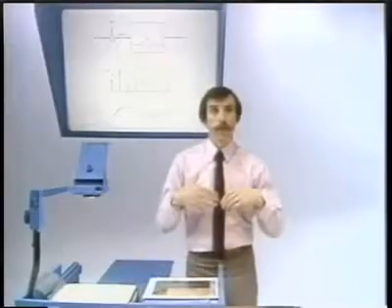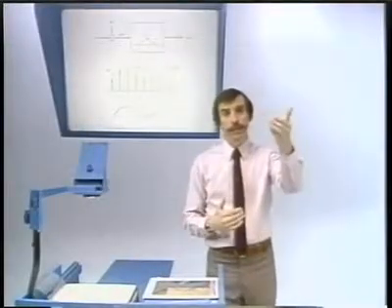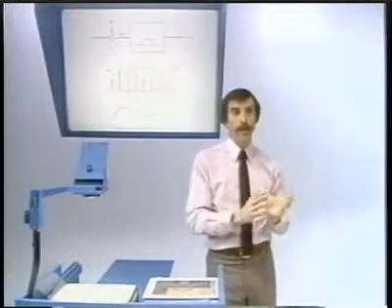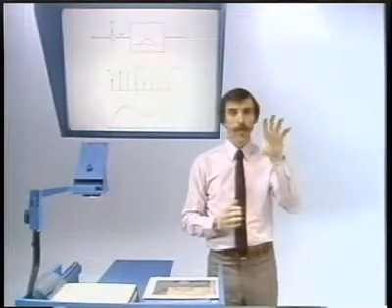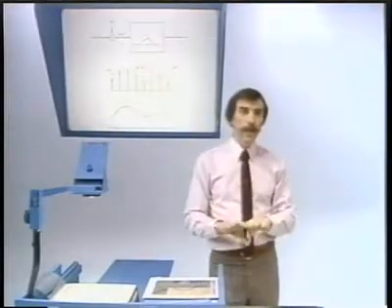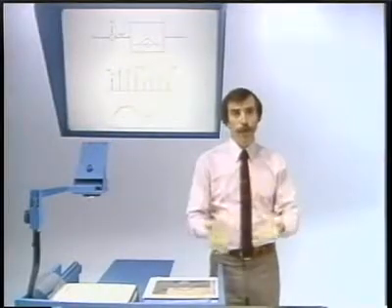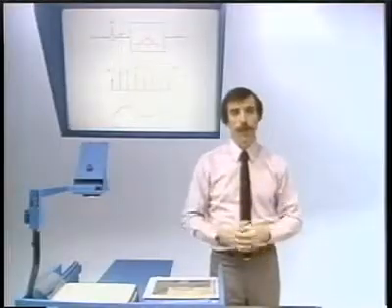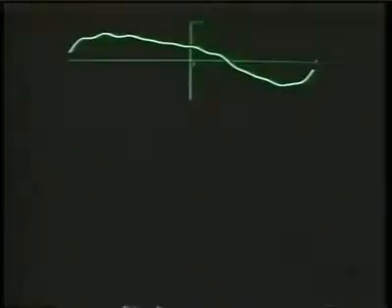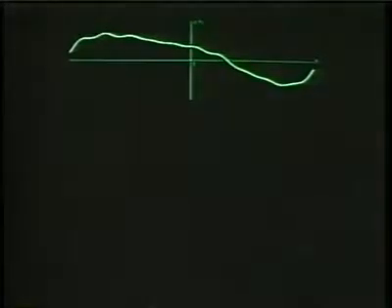So now let's again look at that, remembering that at the top we'll see the original continuous curve, exactly the one that we had before. Below it, the set of samples together with the impulse response moving along, and then finally below that, the accumulation of those impulse responses, or equivalently the convolution, or equivalently the reconstruction. So we have the same continuous time signal that we used previously with band-limited interpolation, and in this case now we want to sample and then interpolate first with a zero-order hold and then with a first-order hold.